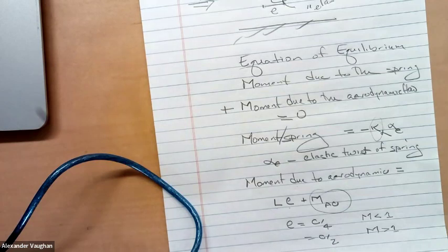How can it, I know about the aerodynamic center, but how can it be true that the moment is not dependent on angle of attack? Because as you pitch your airfoil, the center of pressure is moving along and that changes. It's true if the angle of attack is small enough. It doesn't depend on the angle of attack if the angle of attack is small enough. Okay. And how small is small enough?